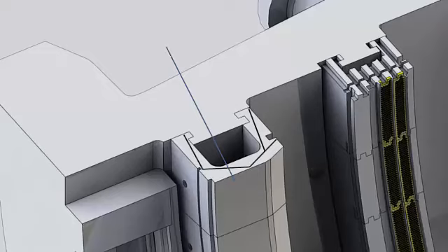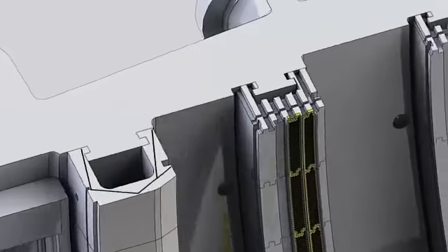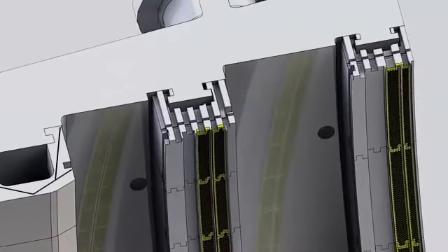The first stage shroud is coated with thermal barrier coating to withstand the extremely high temperatures at this stage. The second and third stage shrouds have teeth that mate with teeth on the tip of the second and third stage buckets. This labyrinth seal minimizes tip leakage.